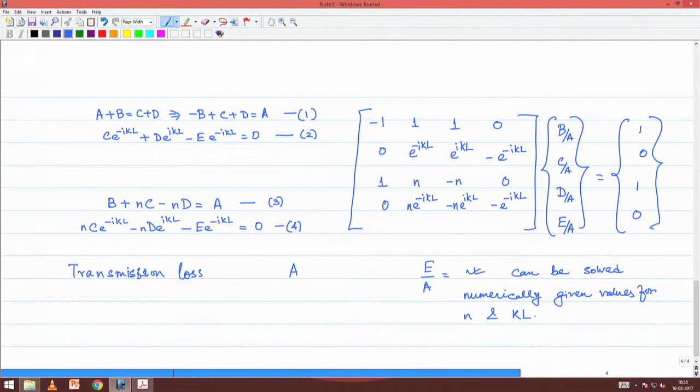The transmission after you put the muffler is E, right. So, but then this ratio you should not just look at it in a linear fashion, but it makes sense to look at it in a logarithmic fashion, right, because we understand that our sound perception is in terms of decibels, the human perception is in terms of logarithmic scale rather than in terms of a linear scale.